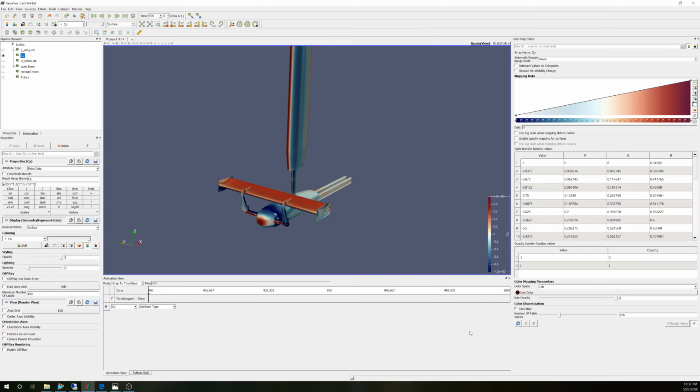And the reason is because you can compare at different velocity settings, and you'll be able to see what's going on, and velocity doesn't come into effect. Because if you really want to know the equation of how we're finding CP, I'll just slide this over, and people on YouTube can already see it. But what you're looking at is, you take pressure, you divide it by 1/2 rho v squared, and that'll actually get you CP. It's very, very easy to do.